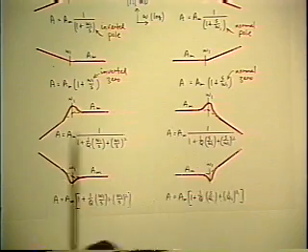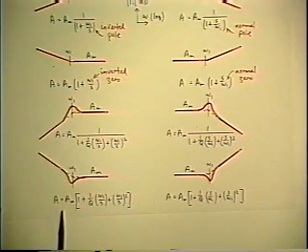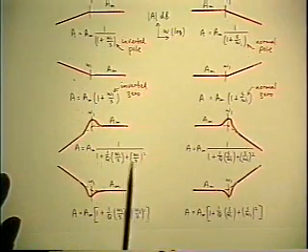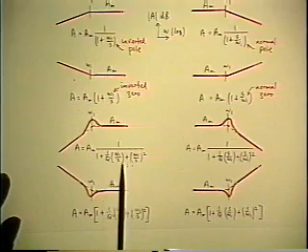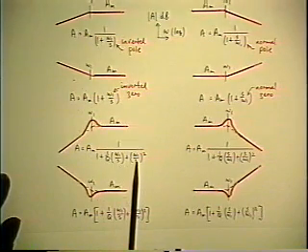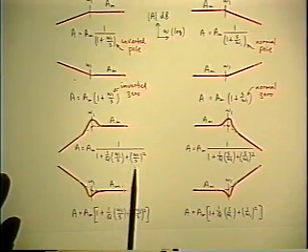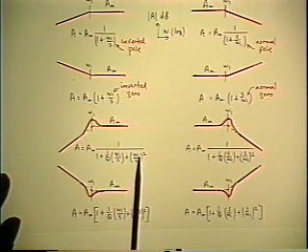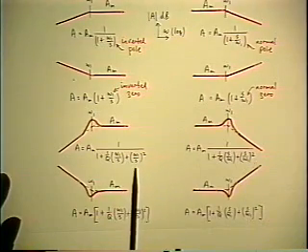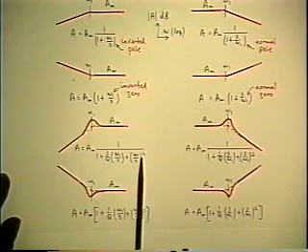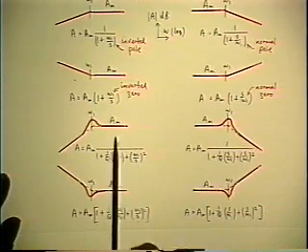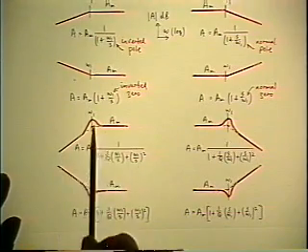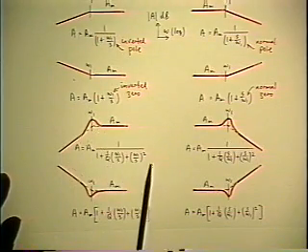But the same thing also happens in inverted form. By reversing the frequency axis, here's a pair of inverted poles. The quadratic is still in the denominator, but the S terms are inverted. It's simply a redefinition of the variable. Instead of having normalized S over omega 1 as the variable, you have omega 1 over S as the variable. But the properties of the quadratic stay the same. And it simply corresponds to reversing the direction of the frequency axis. And again, you can get a complex pair or you can get a real pair.